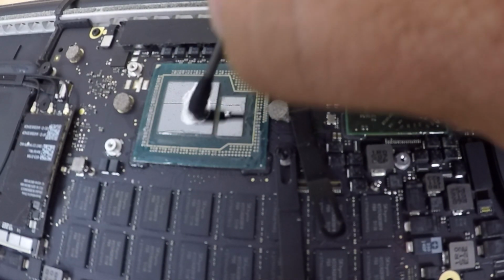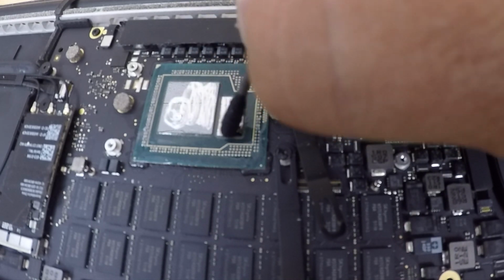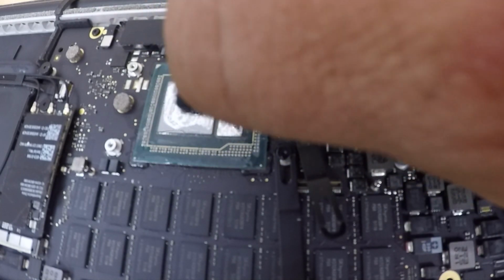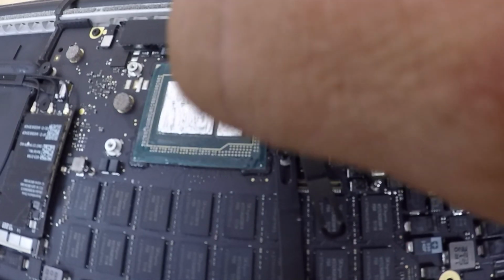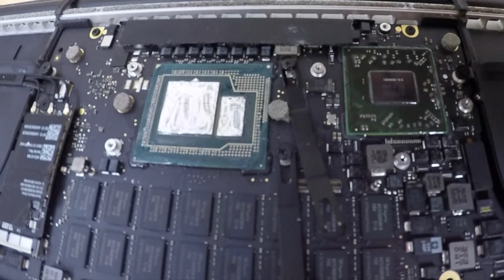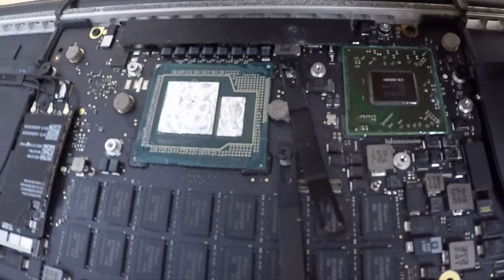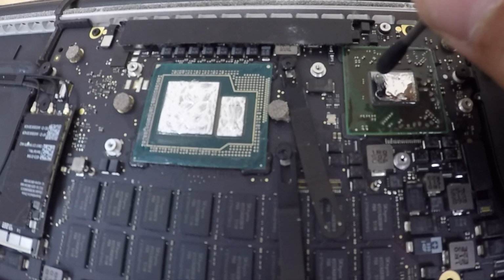You're going to want to take the liquid metal and apply a very teeny dot on your CPU and GPU die and take the Q-tip that came with the Thermal Grizzly liquid metal package and spread it evenly across the surface of the CPU and GPU chipset. Now keep in mind, if you see puddles or have any excess come off, just immediately clean them up and make sure you don't have too much on the chips themselves.